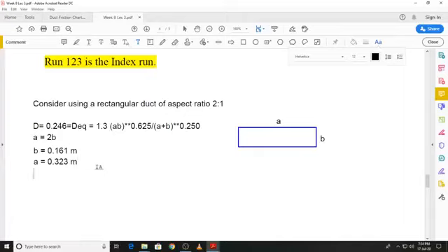Remember what I had mentioned earlier, that if we replace a circular duct with a rectangular duct, we will end up with a higher cross-sectional area, and we will also end up with a larger surface area, and that can also be verified for comparison purposes. If we have a circular duct, then the cross-sectional area, which is pi d square, we had already worked it out as 0.0474 square meters,